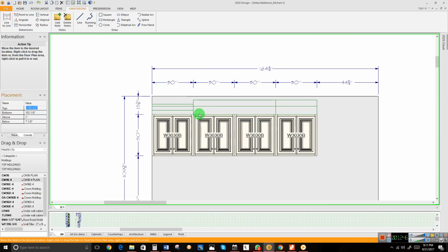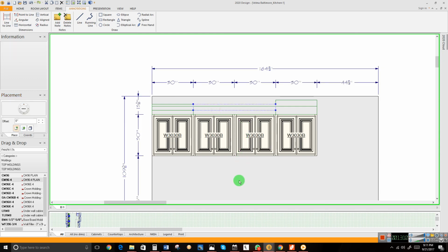What's going on? You need to hold your control key. Press the control key down, and then it can go down. The purpose of the control key is for it to bypass the obstacles. So if you do it down, you can see what's going on. It wants to snap. Once you left click, it will automatically snap to that end. Easy. Now the other way is the best one.